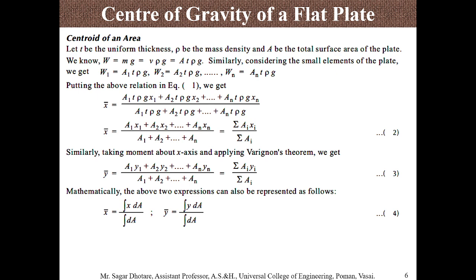A is nothing but area, and y is the distance. Now mathematically we can find the expression: x bar is equal to the integration of x dA divided by the integration of dA. A small area dA has been considered, and it is integrated.